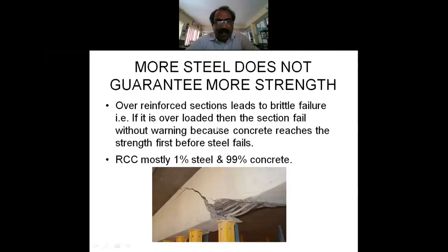More steel does not guarantee more strength. People think in RCC, sometimes, sir, your column sizes are bigger, so put more steel and reduce the column size. Number one, the stress level will increase. Number two, if I put more steel, what happens? Steel will be comfortable, but concrete will not be comfortable. Concrete will crack. Concrete is a brittle material. So it is like coffee. In coffee, decoction is steel, milk is concrete. If the decoction is good and the milk is not good, you will not enjoy the coffee. If there is more decoction, the coffee is bitter. That's just an example I am giving.